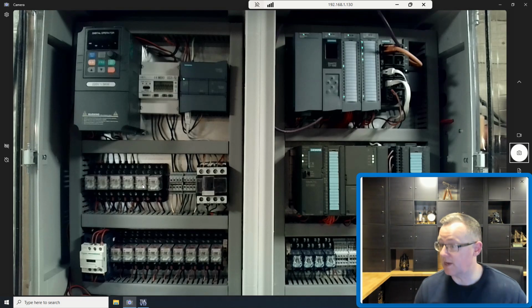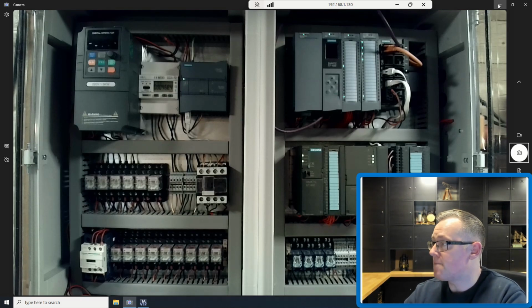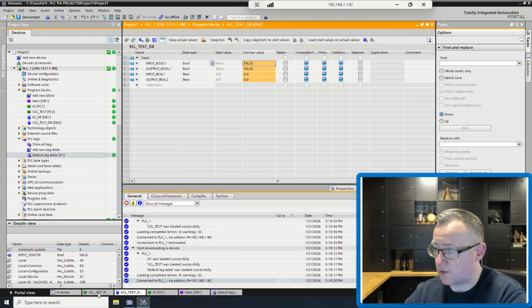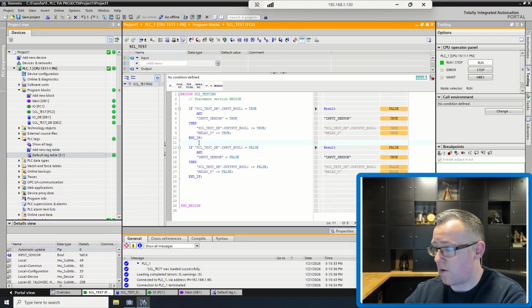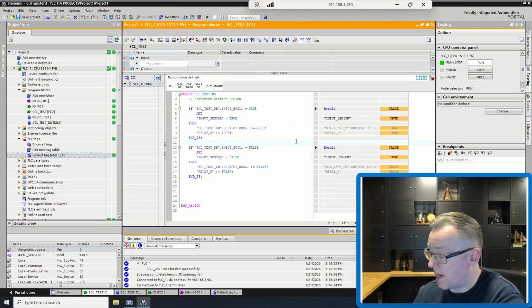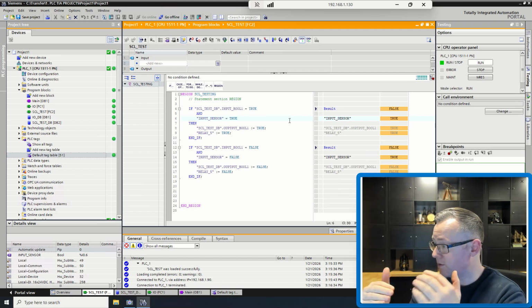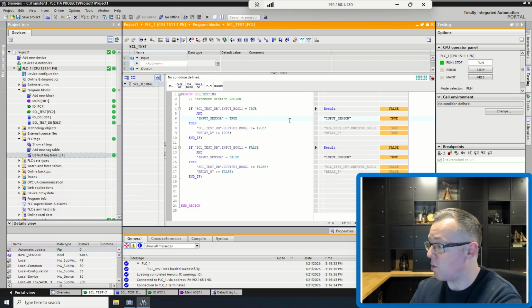So that is an example where, I'll just go back and do a summary of it, we have the structured text logic here, where we have an if statement. First of all, the if statement only had one condition, and then it was altered to have two conditions, where something could only execute in real time once a second condition came in, and both of those conditions had to line up, otherwise both were skipped.